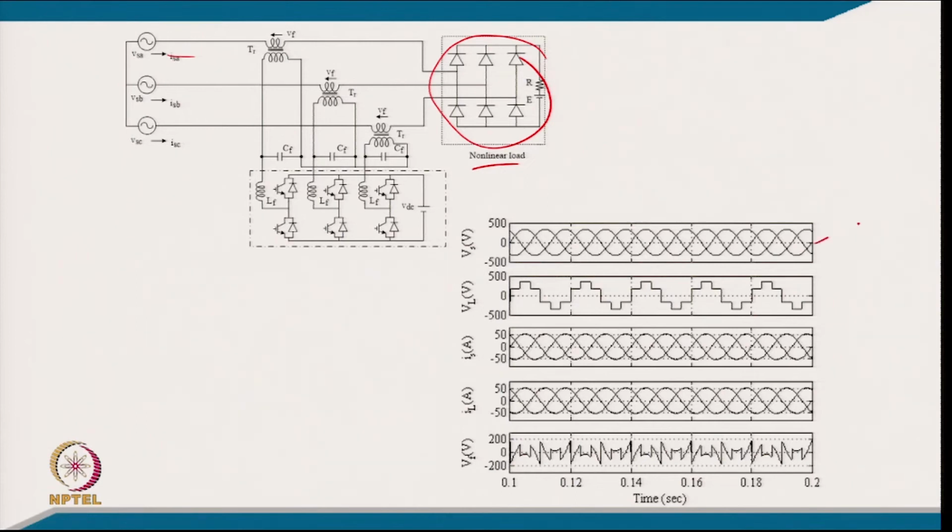So, the supply voltage is, let us say, a sine wave 3-phase balanced supply voltage. If we inject this kind of phase voltage, we will be able to force the supply current to be a continuous sine wave, and the same will be the load current at the PCC. The difference of these two voltages we have to inject. If we inject this voltage, the current will be automatically forced to become balanced sinusoidal, and it can be maintained in phase with the supply voltage. So, this series active filter is virtually working to eliminate the current harmonics of this voltage-fed kind of load. However, we call it a series active filter, which should really eliminate voltage harmonics, but here we are eliminating current harmonics by injecting the appropriate voltage in series with the line.